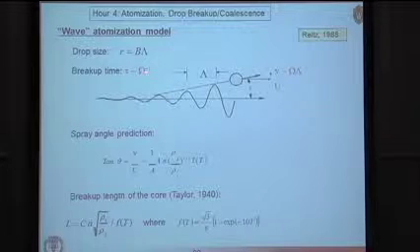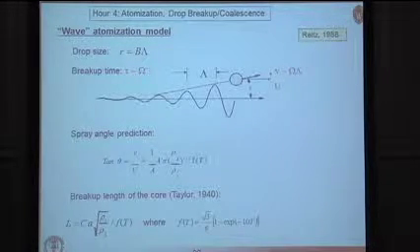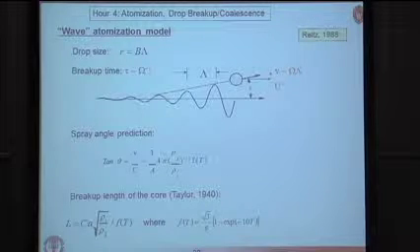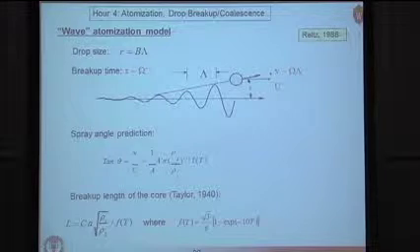But the most important one is the constant that relates the breakup time to the predicted growth rate. And so in the spray models, there's typically a constant that is varied, and it has to be changed basically to account for some of those cavitation processes that we saw in the nozzle that essentially excite or initiate the growth of these unstable waves.